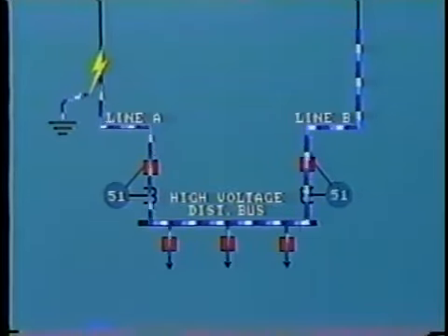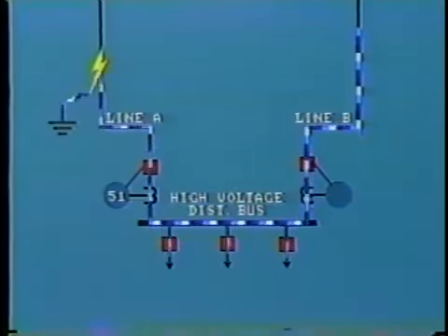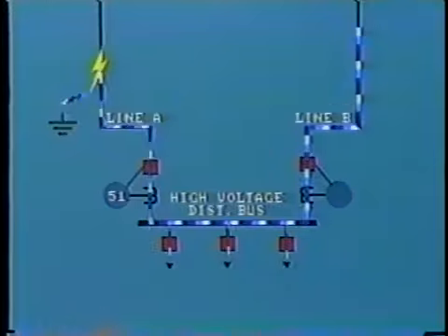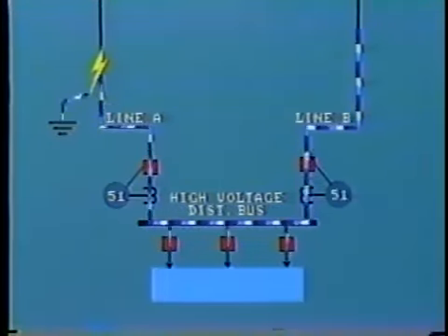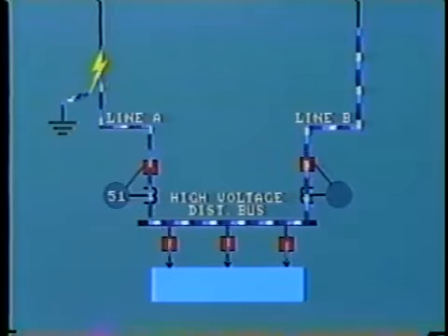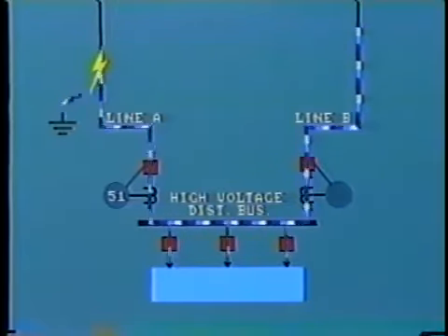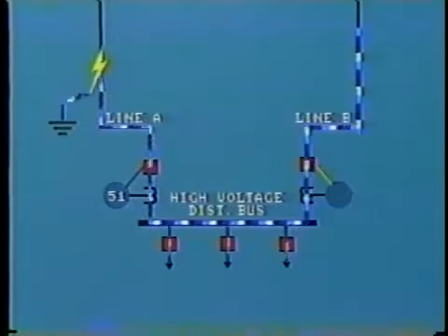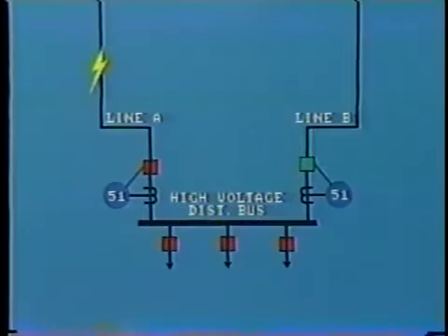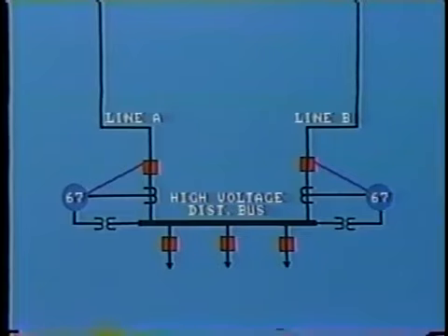Therefore, its own overcurrent relay will also sense the high level current and commence the tripping process. In fact, line B is also feeding the distribution load and therefore passes greater current than A. If the B relay trips out line B, the substation is left without any power supply at all. We can avoid this by using directional overcurrent relays, device number 67.